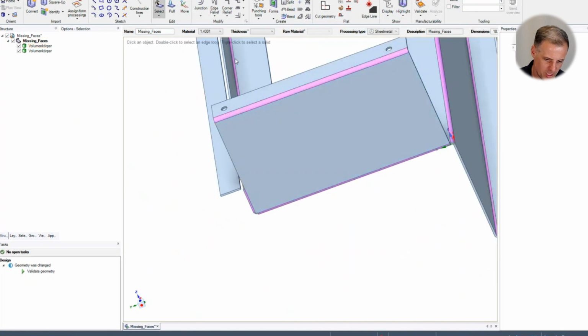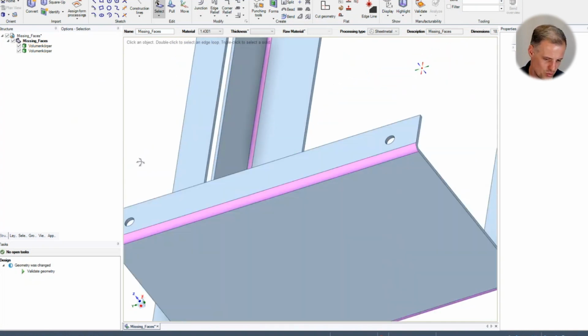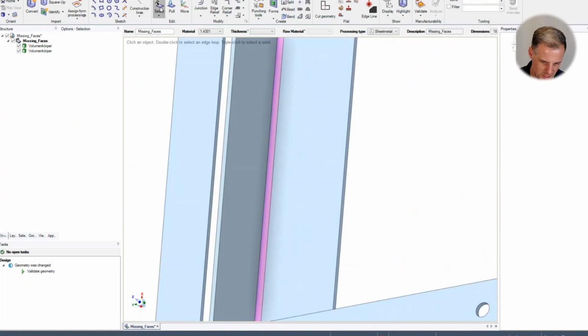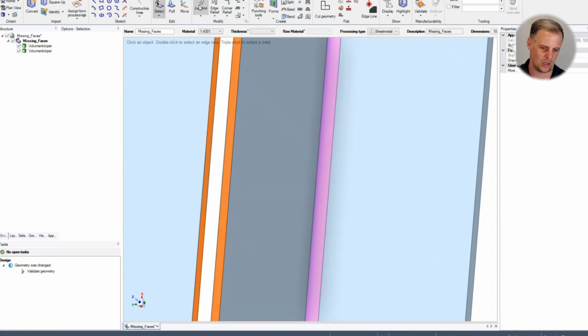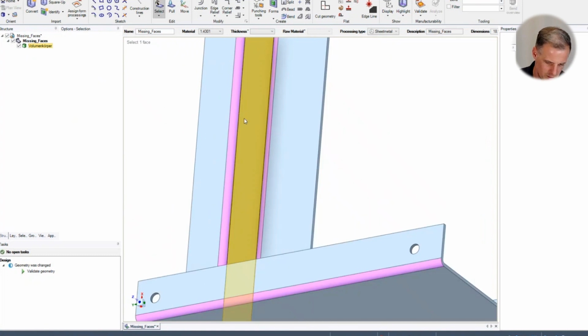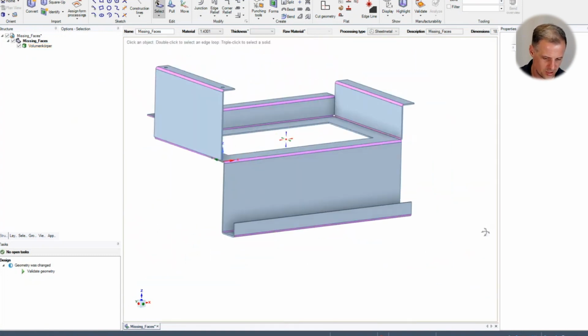And as you may notice, when I'm connecting different solids with bends, it minimizes the number of solids in my structure tree. So one is still missing. Again, select with the control key the 2 faces, and with the junction tool, I can then combine these 2 solids.